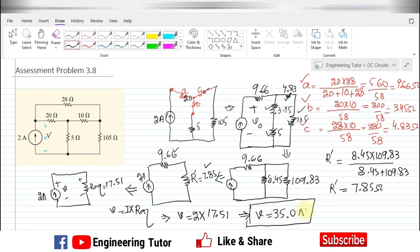Let me write the unit here. So this is 35 volts, the voltage value which we have obtained from this circuit. Initially this circuit was very daunting to us. We converted it into the star configuration, and then after finding the equivalent resistance, we found the value of the voltage.